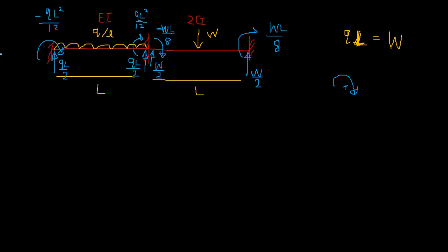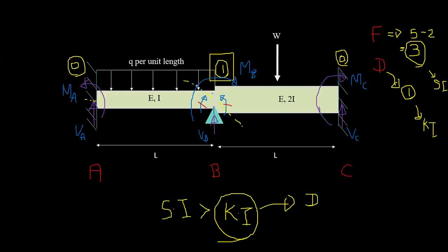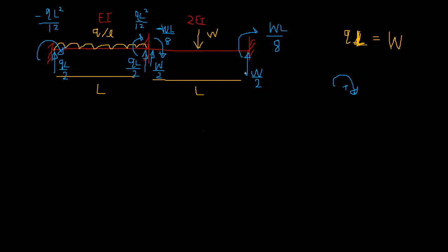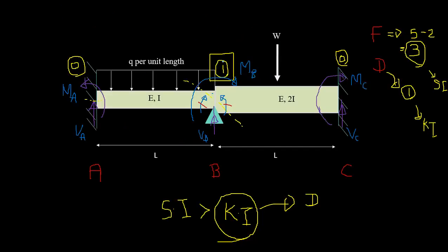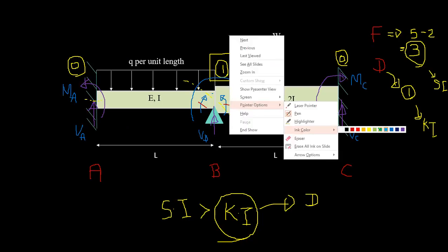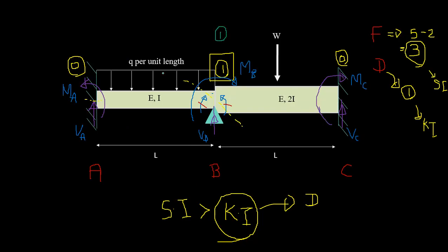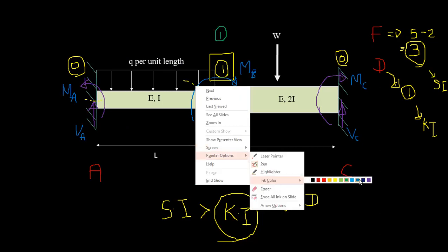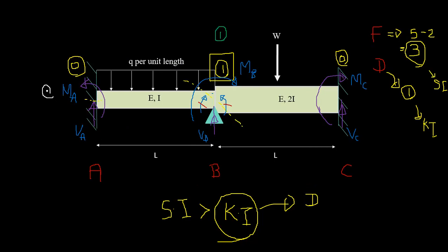So in the displacement method, we use the equilibrium, right? For the equilibrium, we solve, so we need the total bending moment. So we consider the total displacement, right? So this theta, and the corresponding bending moment is the total bending moment, MB. So yes, this is our primary structure. There's only one coordinate, one redundant coordinate, so I don't think you need a matrix to solve this one. For the actions, I will use a different coordinate system, as this is 1, this is 2, this is 3, this is 4, and this is 5.